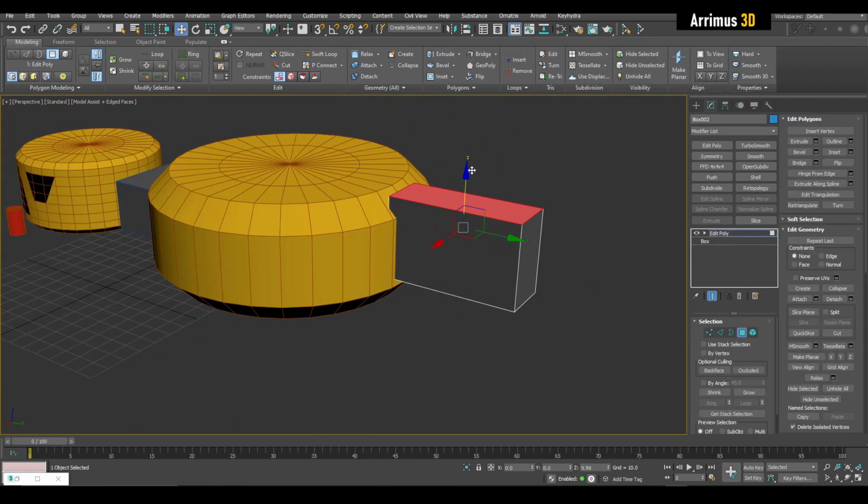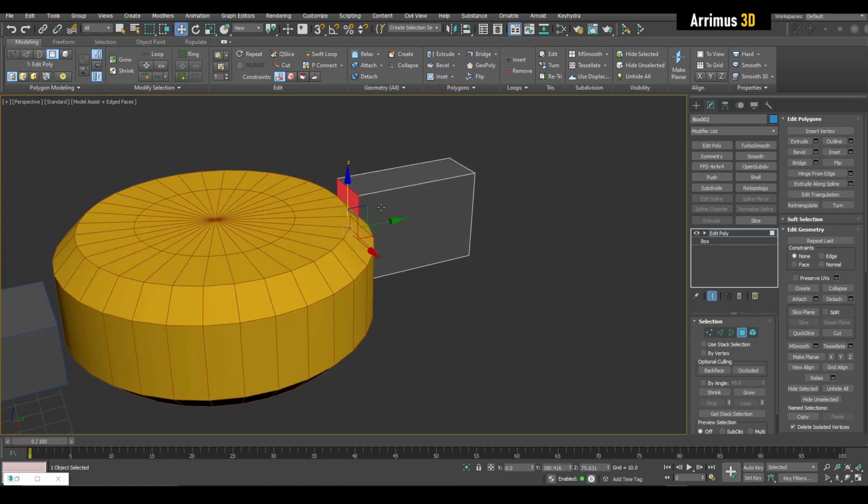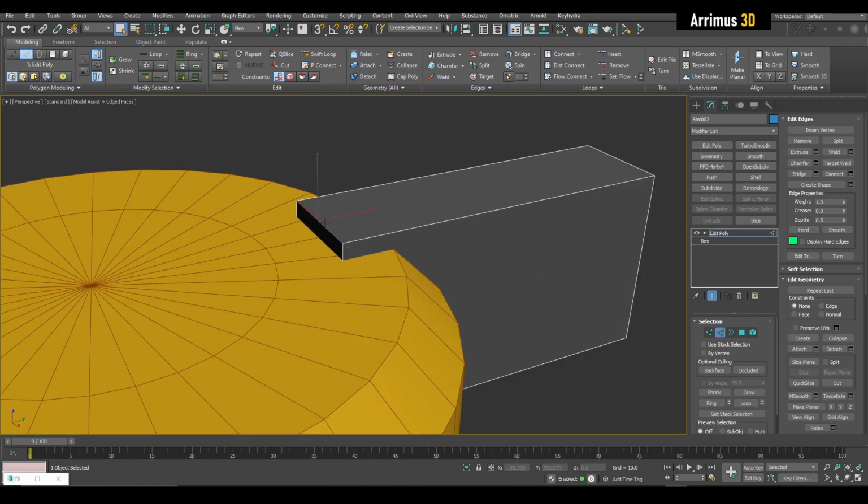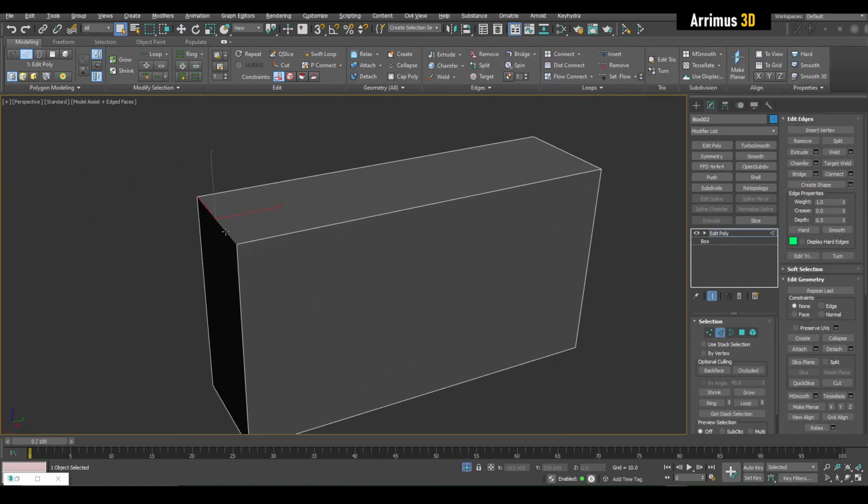All right. And so we're just setting up the basics of the design, guys. No need to focus on crazy details, but we can do things like chamfer this. Now when you chamfer, guys, you can go ahead and hold down Alt, and then once you press your hotkey for chamfer, you can set up a custom hotkey. You can go ahead and press Alt and then move left and right to increase or decrease. Now I'm going to go ahead and left click to confirm that and right click to exit out of chamfer.